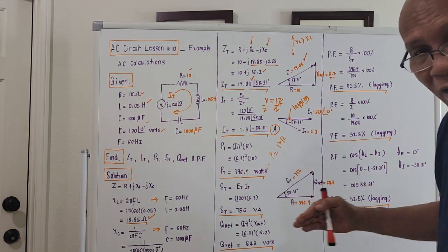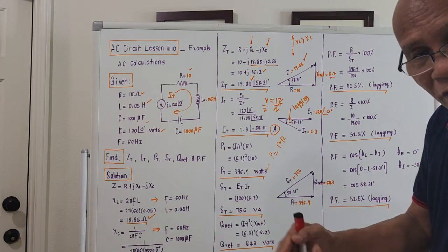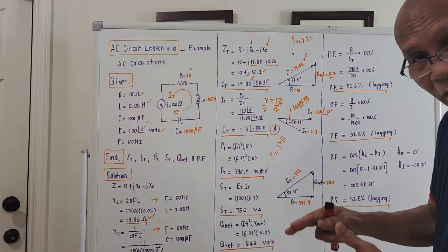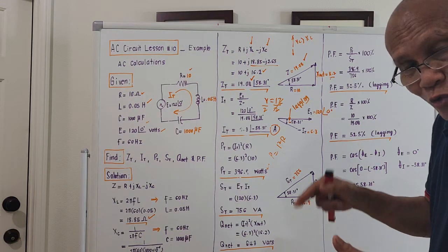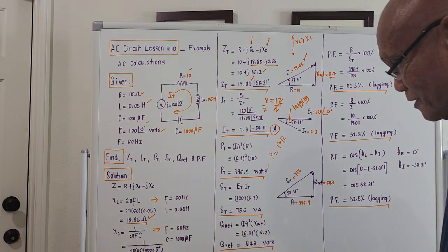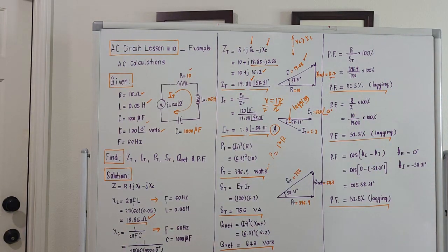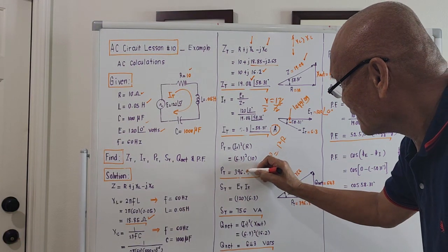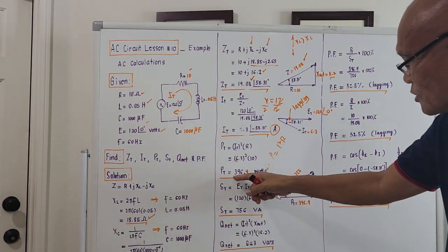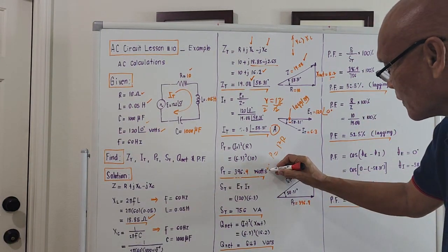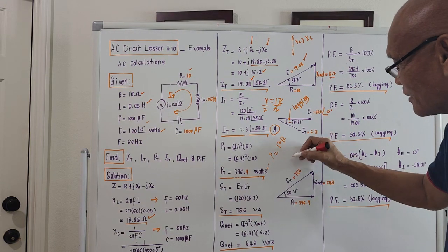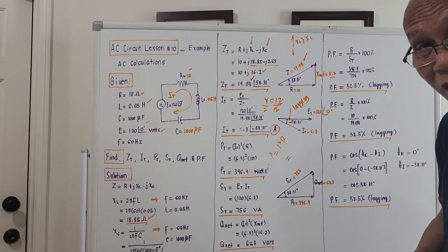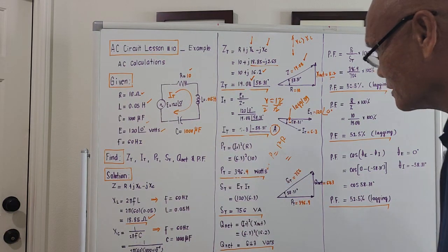Okay, this is actually the one we are paying in the utility companies, because if you multiply this 396.9 by how many hours you operated that one, that will be kilowatt hour, and kilowatt hour is actually energy. So that's what we are paying in the utility companies. Okay, but it's a must that you should know how many watts first. Because if you use this one for 24 hours, you multiply this by 24. Okay, that will be your total bill to the utility companies.